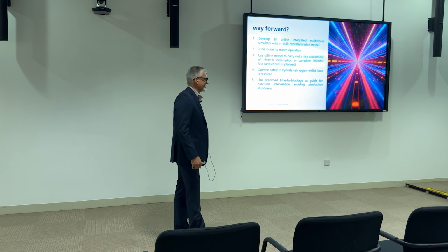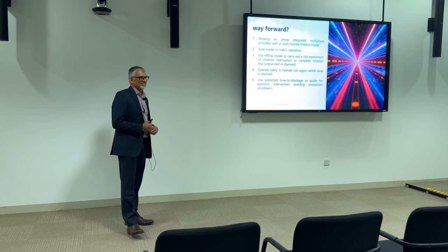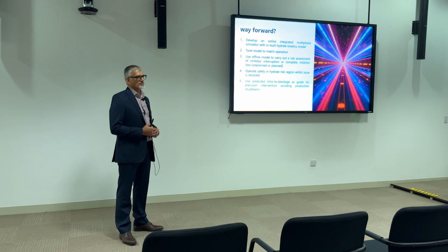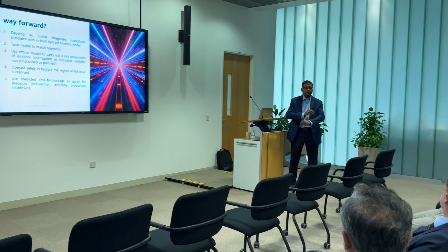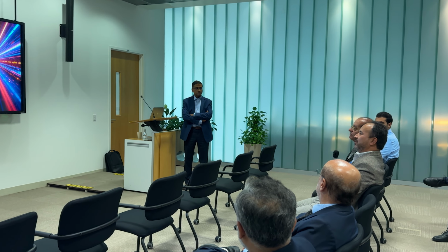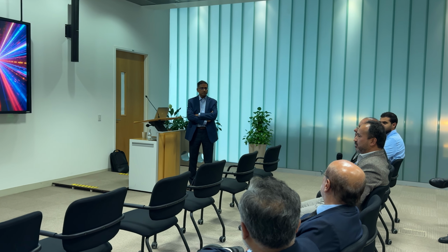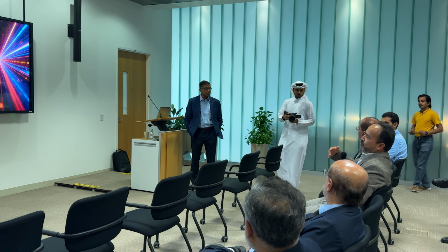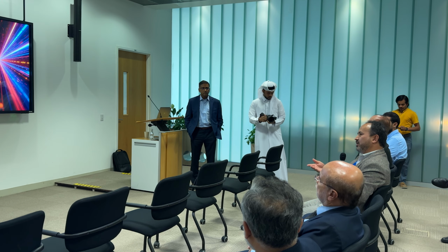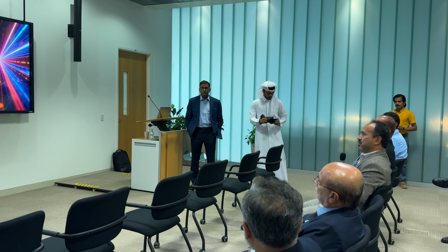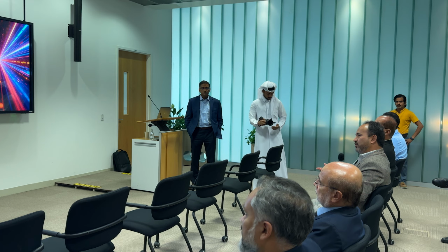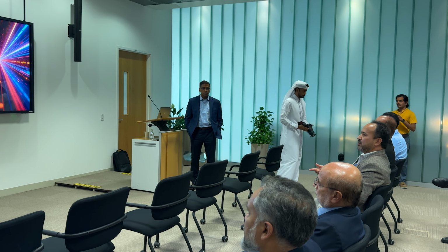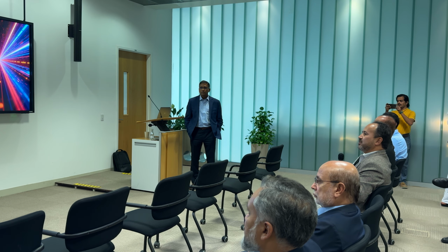Thank you very much, Ashfaq, for the nice presentation. Mahmoud Nazari, I'm from Qatar Energy Agency, Head of Flow Assurance. So one question is the risk of operation in the hydrate zone. You are talking about the kinetics. Have you considered, if we operate in the hydrate zone and hydrates flow inside the pipeline, any risk of flow-induced vibration due to the larger amounts of hydrate pieces inside the pipeline, or extra erosion risk inside the pipeline?